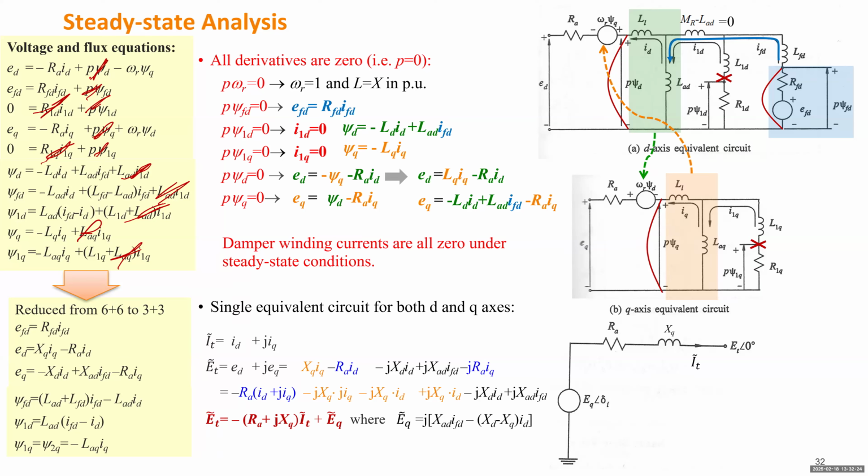So you can have a power system operating at like 55 Hertz, right? If that's the case, it will not be 1. But for BPS or BES, based on the NERC standard, that frequency should be very close to 60. And if you consider automatic generation control, that frequency needs to almost always go back to 60 Hertz for any static condition. So it may not be an accurate model, right? Maybe.